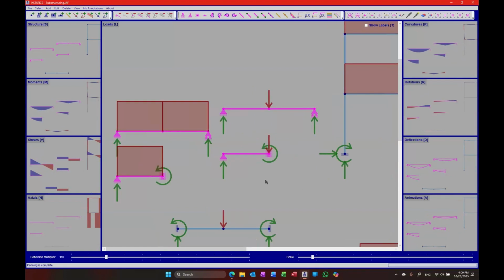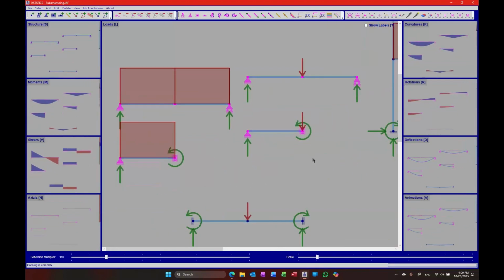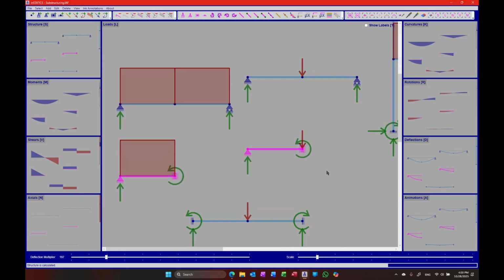Okay. So take a look at this structure here, right? You have a simply supported structure and you have a distributed load on it and a point load in the middle of my simply supported beam. Because this is a symmetric beam, if I don't want to invert a very large matrix, in this case it's not going to make a big difference, but see, I have 3 degrees of freedom here, 3, 3, so this is going to be what?